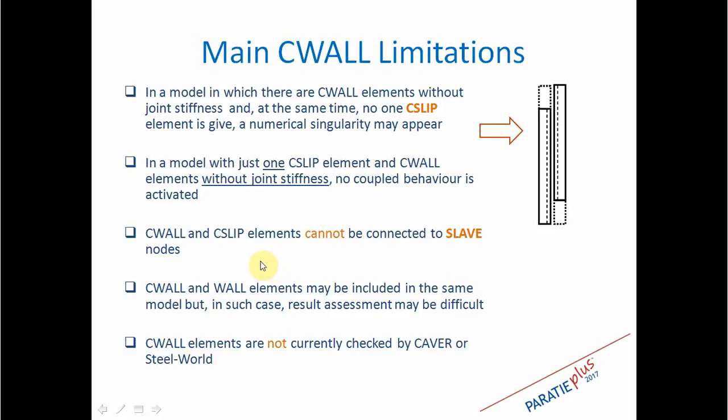And what I recommend is that once you decide to use CWALL elements, it is better not to mix this element with the ordinary beam elements, because of course it works, but the results assessment may be a little bit difficult. You may have some questions to understand how the equilibrium is respected.